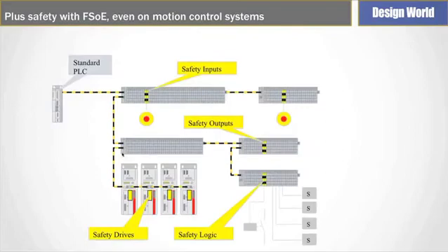One of the things that was developed along with EtherCAT is the Functional Safety over EtherCAT, FSoE, specification, which allows EtherCAT to act as a carrier of a black channel safety protocol and allows you to distribute your safety devices along the EtherCAT backbone using a standard PLC or PC architecture, along with lots of non-safety rated I/O. And then you have a safety logic controller out in the field, or multiples, and safety inputs and outputs that are linked logically to the safety logic.